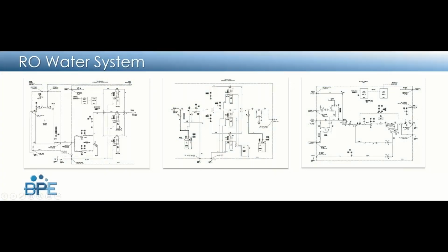In this case, this is really your pretreatment stream at this point. Very often, if you don't have sufficient water pressure coming into your RODI system, you may need a booster pump. You generally want to have about 60 to 70 pounds of pressure to be able to get through water softeners. In this case, we have metabisulfite injection in place of the chloramine. Then you have your multimedia filters, and then multimedia metabisulfite water softeners. Then you have your RO system here. And this really would constitute the entirety of the pretreatment system, where you're doing, again, the majority of your work. But you can see everything here is really leading up to the actual RO system in this case.